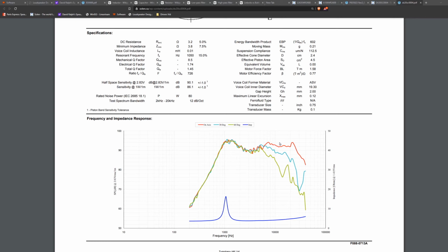And as far as the high frequency goes, I'm probably going to lower that a little bit so it's more in line with being flat, but probably straddle it a little bit above the true reference line, and that will give additional reinforcement to the off-axis response, so that even sitting off-axis, the reduction isn't as great. By straddling the main reference audio line between the two, it will give a much better listening experience for everyone by not totally focusing on one particular point.